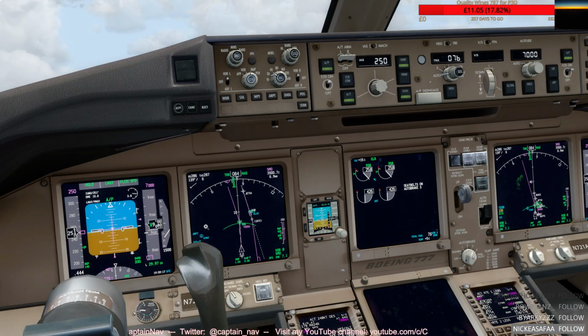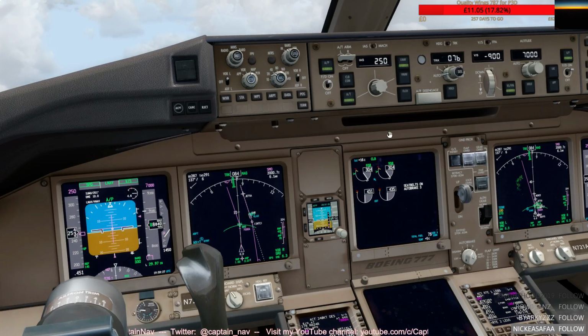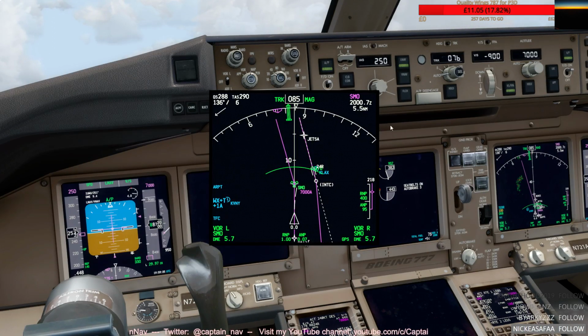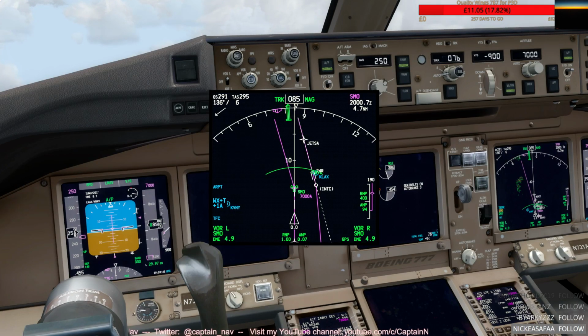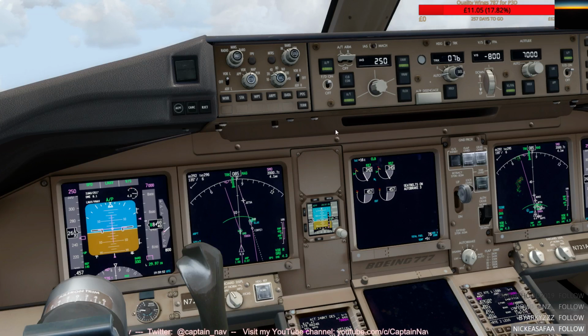Otherwise, if I don't want to go down so quick with the flight level change, then I can go vertical speed. At the moment it's giving me 1500 and I can reduce it, let's say, to 900 feet per minute. And then with the green banana, as I call it, the altitude range arc, you can see more or less where you're going to reach 7,000 feet. At the moment it's changing a little bit with the speed and stuff. Yeah, does it make sense?